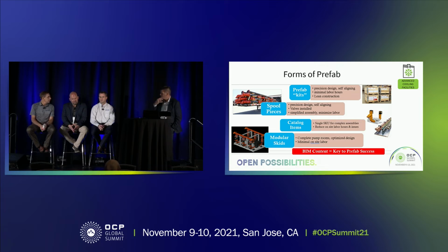And I think also the assembly on site is a big piece of this as well. There's so much data center construction going on right now that anytime we talk to any of the contractors, everybody is stretched thin. They're having trouble getting pipe fitters, they're having trouble getting electricians, and so on and so forth. One of the projects I'm working on right now, where we're looking at prefab, we looked at 1 row of piping distribution for a liquid-cooled application. If everything is stick-built in the field, I believe it was approximately 180 joints that had to be made up down the length of the row. If we prefab it, ship it to the site on skids, and hook it up in the field, it's 8.